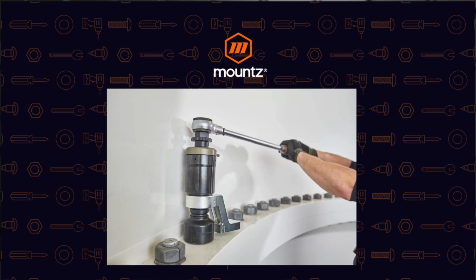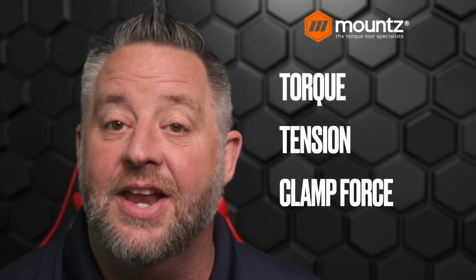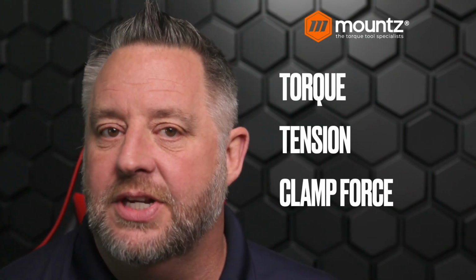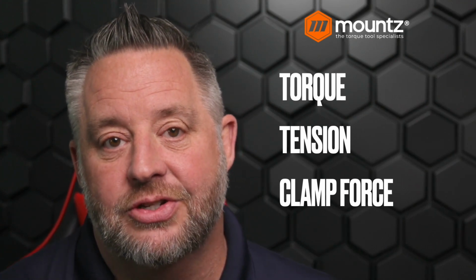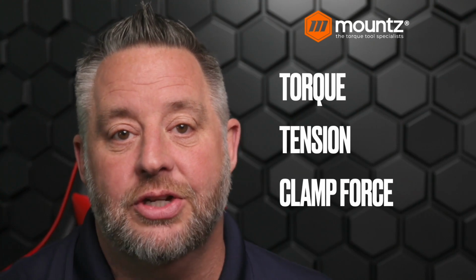So again, that brings us all the way back to the beginning of why we use torque. And if there is anything that you get out of this presentation, I hope it is this: that we use torque to generate the tension in the fastener to create the clamp force that we need to make sure that our assembly stays together and doesn't move, because any type of movement is going to create wear and possibly cause our fasteners to fail, or we may be closer to that yield point. Again, with vibration or shock causing those fasteners to fail.